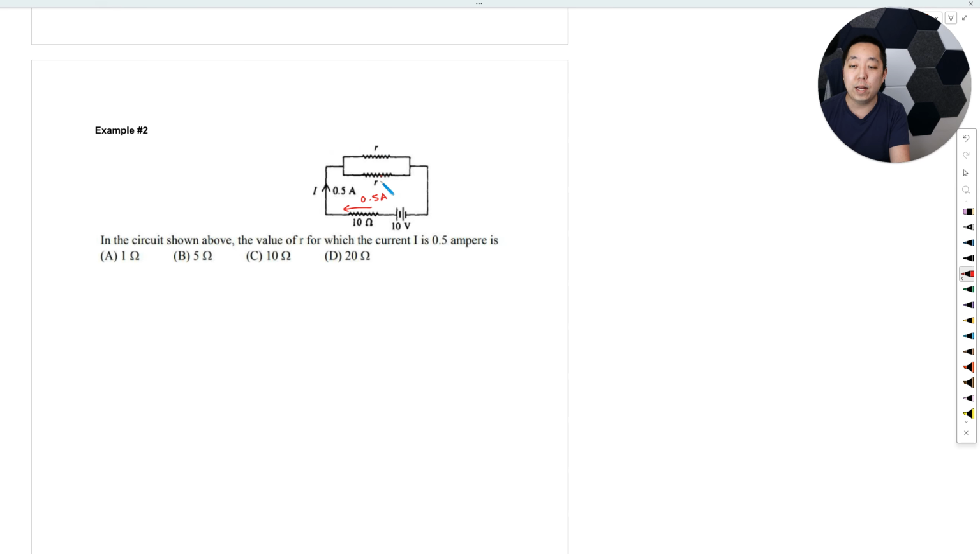And then we might as well combine those into a single resistor, and those are parallel, right? Because they share nodes, so 1 over R equivalent would equal 1 over R plus 1 over R, which is 2 over R. So the R equivalent is going to be R over 2. So then our circuit, just replace it with a single resistor of R over 2, and then again we have the current going through there like that.